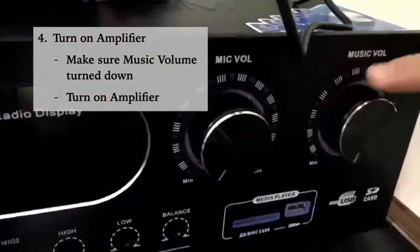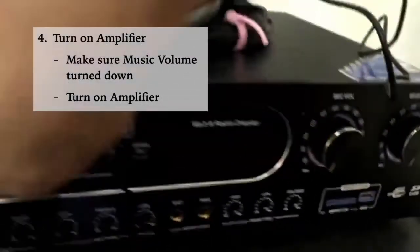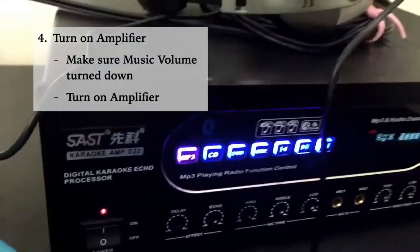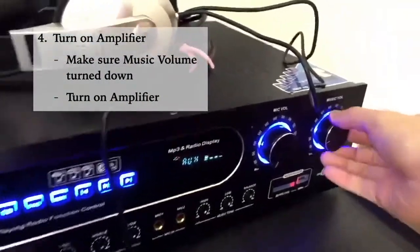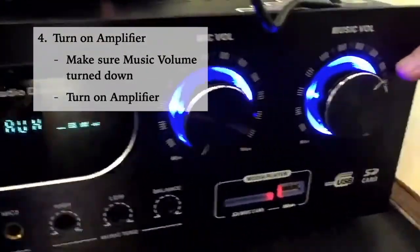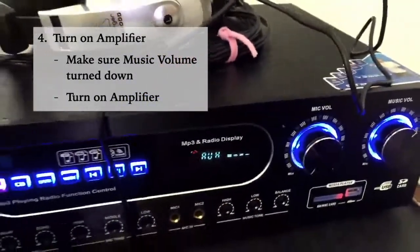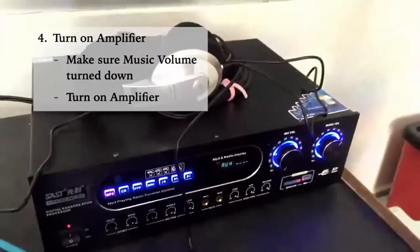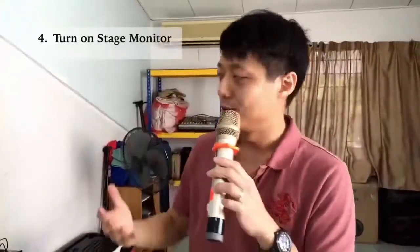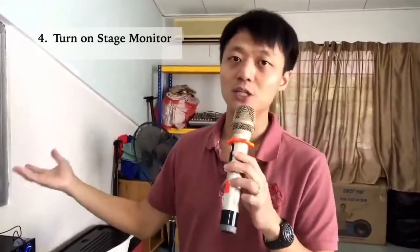The music volume here is set to the minimum. Then only you turn this button on. Now if you turn that button on, you see it lights up in blue. Then you turn the speaker volume up to about the 2 o'clock position, up around here. Then the speakers are on already. So this is the way to power up the whole PA system without causing damage to the speakers. Then now only you go downstairs to the stage and turn on your stage monitor speakers.